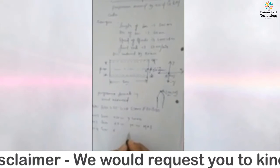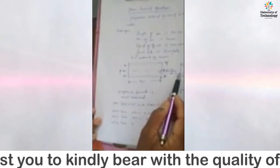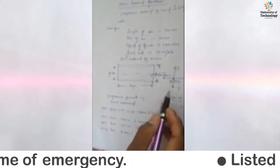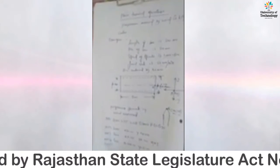Then X and Y coordinates put 0 to 200, and that is negative X. So here minus 200, and the depth of cut is 2 mm, that goes minus X. The positive X is on the operator side, and minus X is the depth of cut. So here minus 2 mm, and line 5